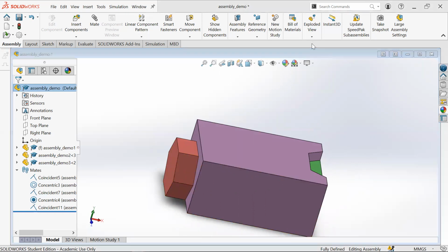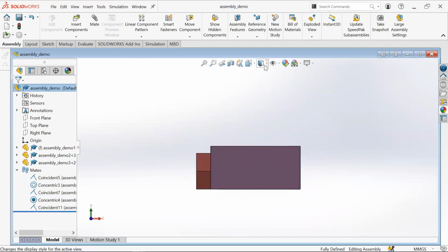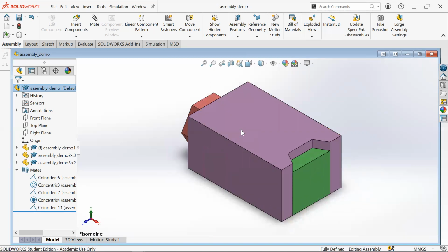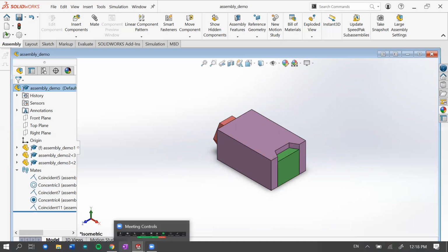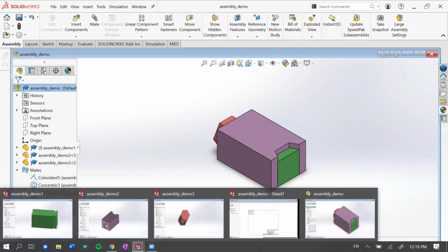All right, so now let's take a look at the exploded view. To make an exploded view, first of all, let me show you what I meant by incorrect orientation. If you go into view cube and choose isometric, you get this. And you don't want that, right? That's a common problem with sketches. You start on the wrong view and you get an isometric drawing view that's oriented the wrong way, and it looks really weird and unnatural, and not ideal, definitely.